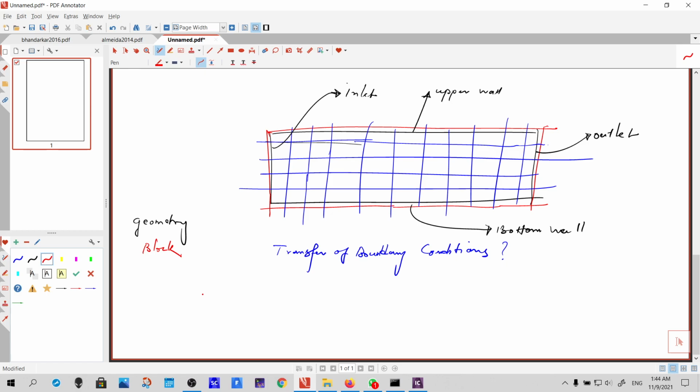These boundary conditions will not be available in that mesh because you haven't mapped, or in other words, you haven't associated, or you haven't transferred the names of these boundaries to the mesh because you have not performed association. So that is the base of mapping or association. That really requires your attention, and that is one of the main two reasons why we do this association. Okay, leaving this talk just here,